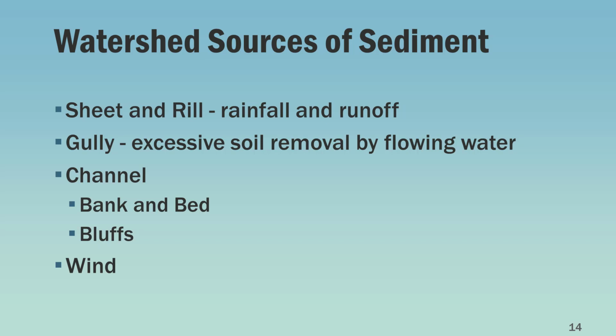This is because of the energy of the stream flow and the shear stresses acting on the bed and bank. When the shear stresses exceed the critical shear stresses for erosion, then you will see a net erosion of silt and clay load from the standpoint of the cohesive fraction. Again, HSPF is a one-dimensional model, so it does not really do bank erosion. It does bed erosion.